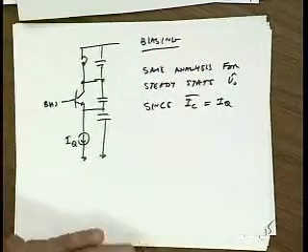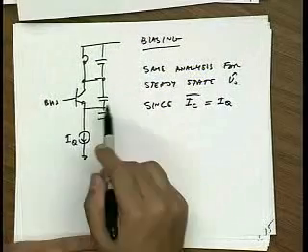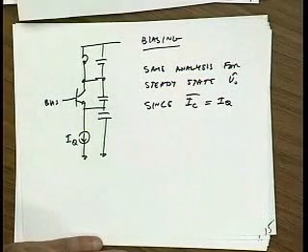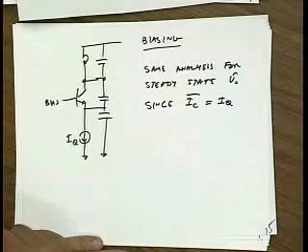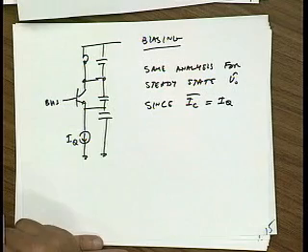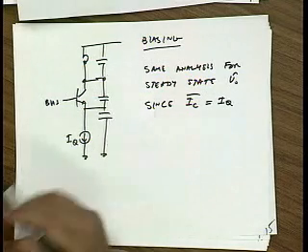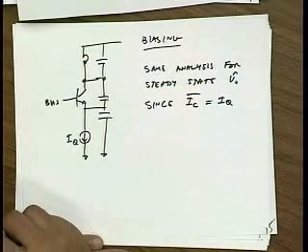Okay? And you can see that this one is a lot more amenable to integration. It almost looks like something you could just pop into an integrated circuit. You've got a current source here, got these capacitors. You can build these capacitors very easily in an integrated circuit process. You can use basically just the metal layers that you get for free and build up pretty nice capacitors here.